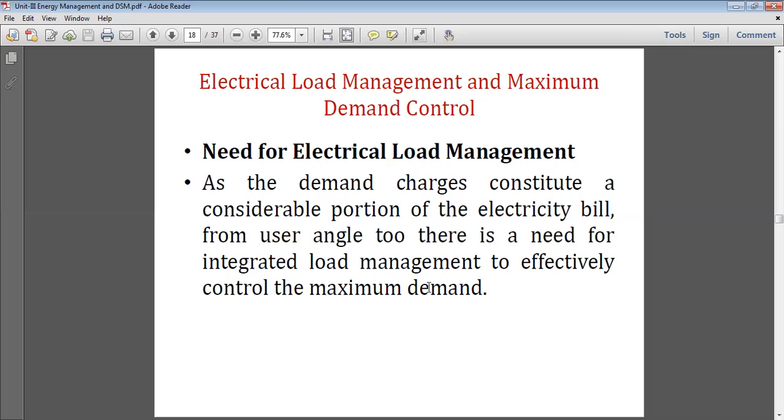This is the first method. The second method is to study the essential feeders and non-essential loads. If you run your non-essential feeders or non-essential loads at night time, definitely we are able to reduce our maximum demand. For example, in any factory, there is an effluent treatment plant and water pumping system. It is not necessary to run your effluent plant in the peak hours, that is 6 p.m. to 10 p.m., or in the daytime. You can shift it into the night time. At night time we get the benefit of the electric rate, which decreases by 1 rupee 10 paisa or 1 rupee 50 paisa.